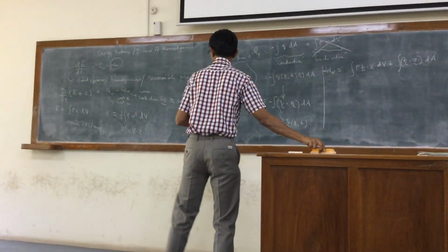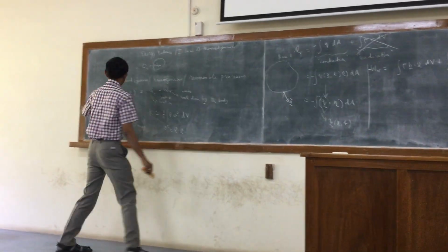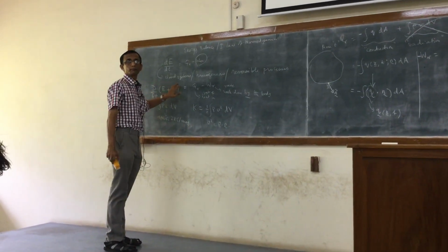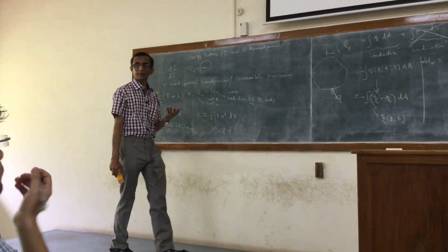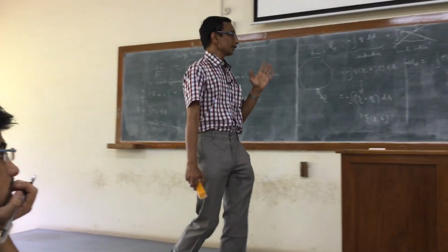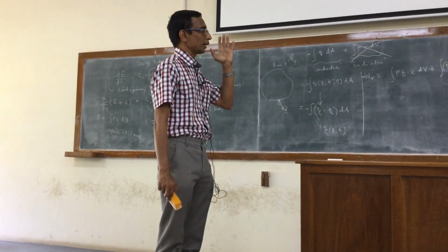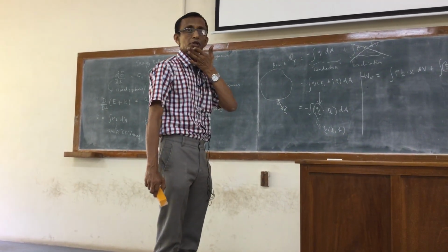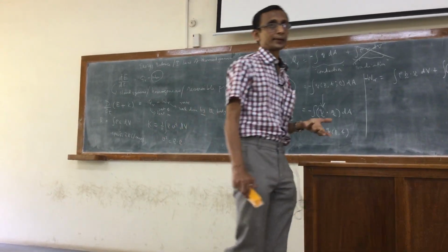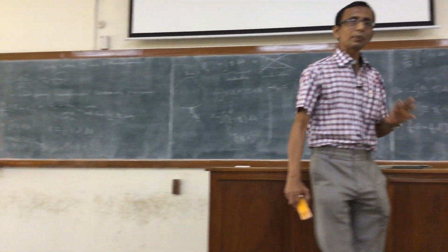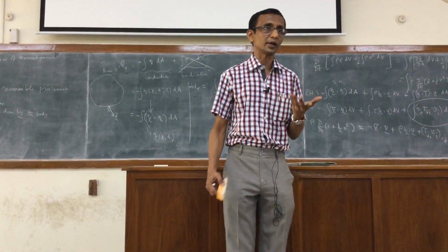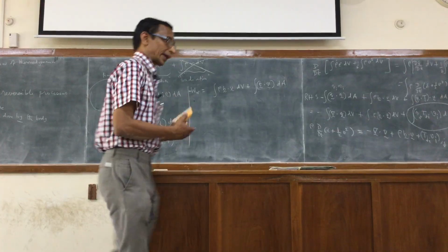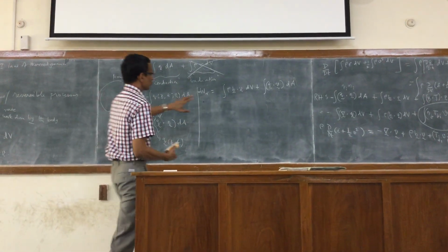The mechanical energy balance looks at dK by dt, that is the time substantial derivative of the kinetic energy. Because if you see in this, we have not made use of the equation of motion. In that sense, this can be regarded as a slightly purer form of the energy balance. However, we have still used the fact that the mechanics contains two types of forces.